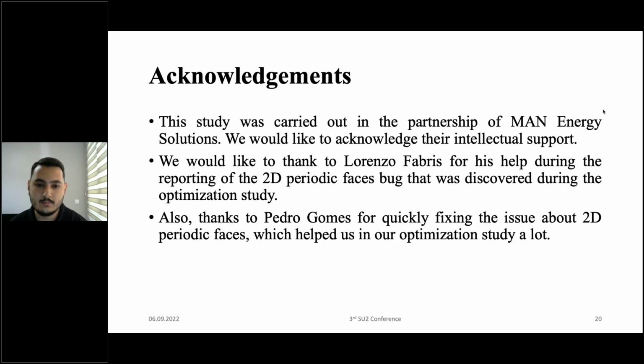Okay. Yeah. Well, we have also suggested implementing the non-reflecting boundary condition specific for turbomachinery applications, which would be much better. Okay, so Matteo suggests using this better boundary condition, the non-reflecting boundary condition for turbomachinery applications. Yeah, which is available in develop, I hope. Almost available in develop.